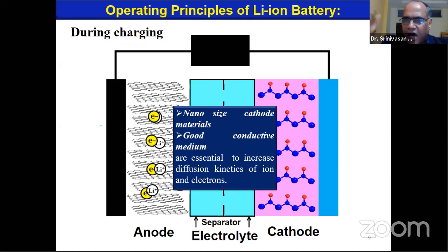Like a lithium-ion battery, the supercapacitor alone we cannot use. For public transportation abroad, they run supercapacitor buses within the city. Every 5 kilometers there is a charging station. The bus gets charged and runs for 5 kilometers. By the time people get in and get out, it will be charged, because it can store energy to travel only 5 kilometers, since the physical phenomenon is involved and only carbon electrodes are there for storing energy. So when you go another 5 kilometers, it runs completely discharged, and then within 1 minute it can get charged again.